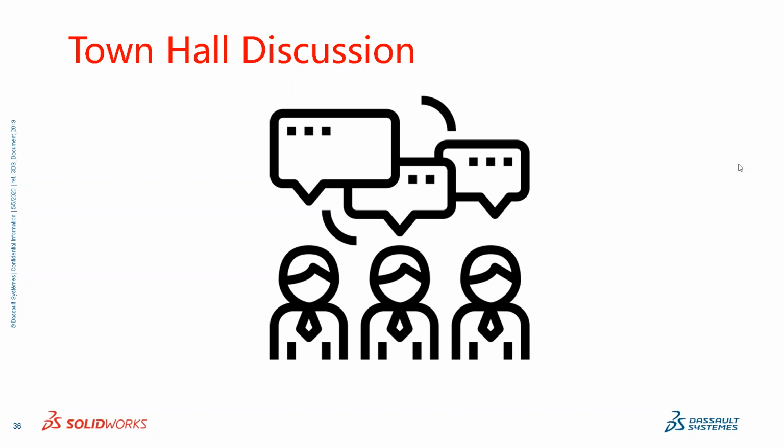On the push-pull feature, does the puller have to accept the push, or can they say no to a change? Even I know the answer to that. No, you do not have to accept the change. And what is nice, and you probably saw it within some of the video that I did, when there was a change detected, whether that change was mechanical driven or PCB driven, within the panel and the collaborative environment, I could accept those changes or not. I actually even get a visual of those changes before I accept them or not. So yes, you do have the ability to accept changes, and then you can communicate that either direction based off of those circumstances.